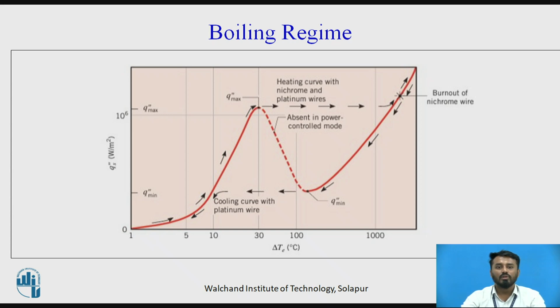Hence, the external pressure applied on that vapor bubble will try to burst it. With the bursting action, immense heat mixing will take place. With that mixing, the heat transfer coefficient will increase. That's why the slope of the curve goes in a strictly increasing manner.